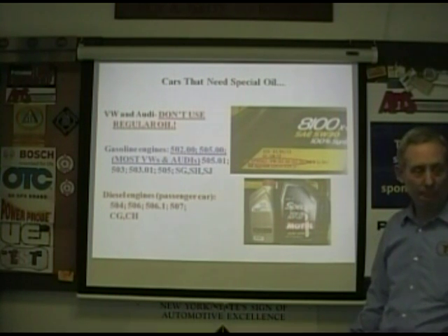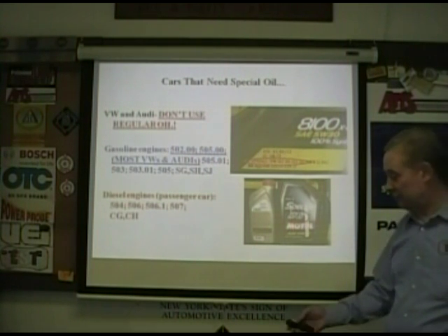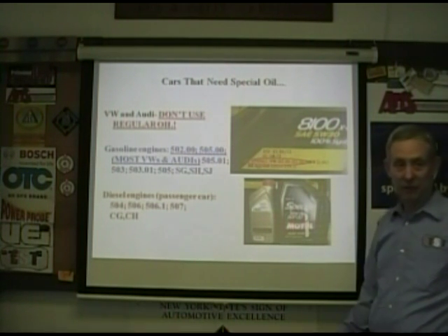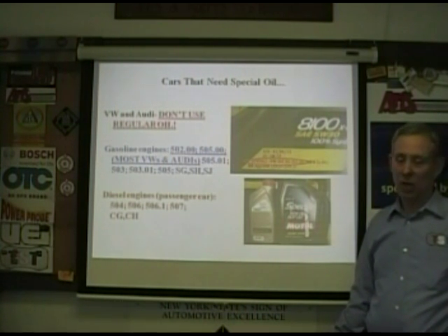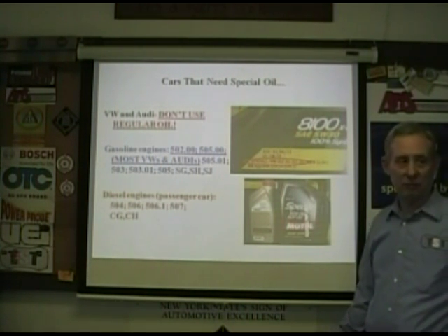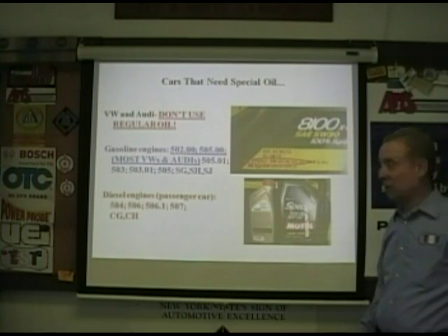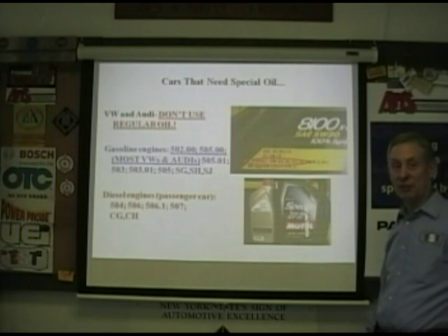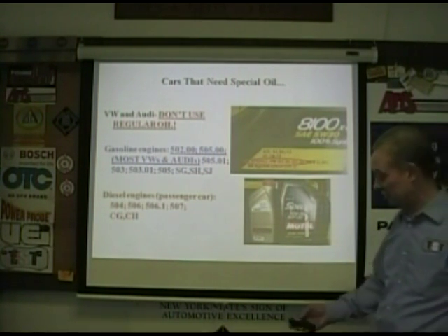So you would say a good starting point, if you do have a code for variable valve timing, the first step is to check the oil. Check oil pressure, make sure it's got the right oil in it, and if in doubt, drop the pan and look for debris in the pickup, because it may be too late at that point. There's no easy way to check what the weight of oil is, right? No, you just have to take it out and put the right stuff in, and see if the symptoms go away. I've actually had that. But in my opinion, anytime you have something like this that you're worried about, you should be dropping the pan and physically examining the bottom to see what's in there.